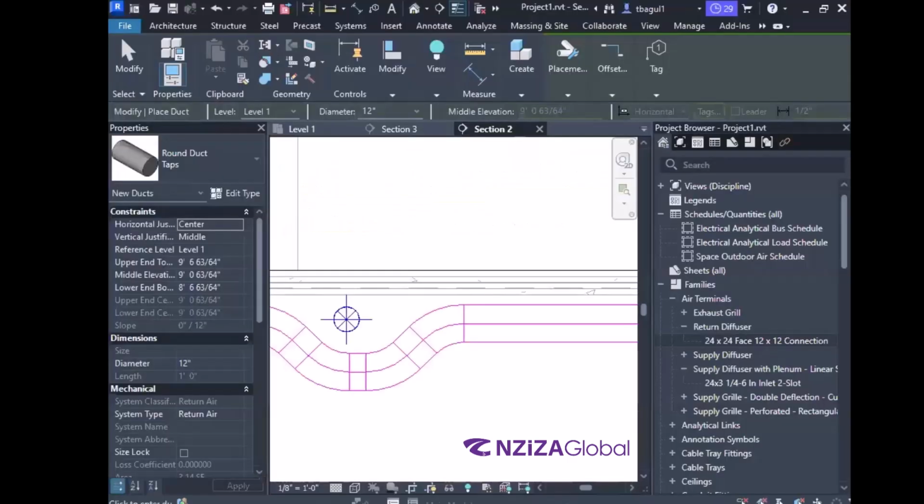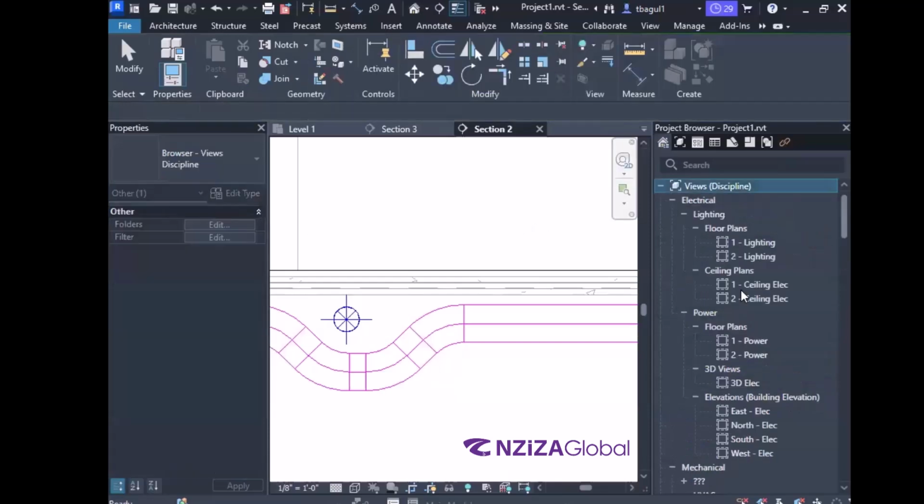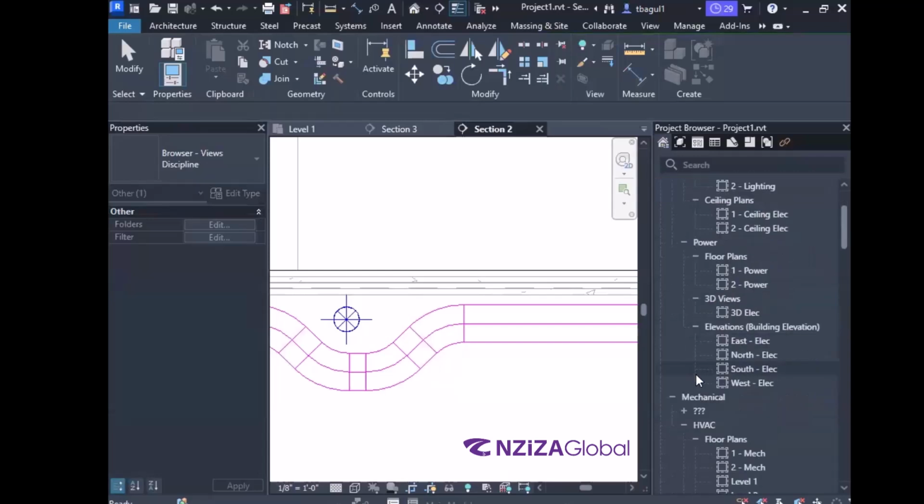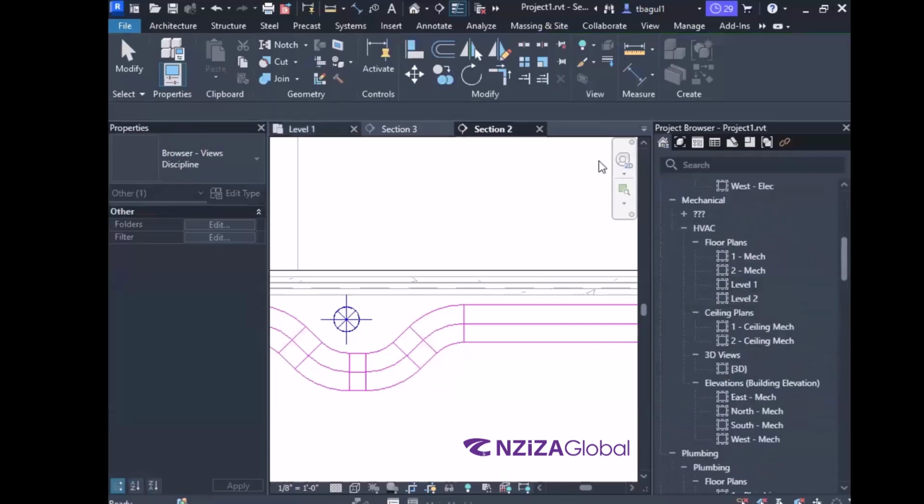Okay. Now coming back to Revit. All right. Now, when we were talking in Revit, at the very beginning when we started the project, we saw there is a mechanical template, electrical template, plumbing template, but we selected the systems template. Why is that the case? Because we want one model for the 3 systems: mechanical, electrical, plumbing. All right. Till now, what we were working on was the mechanical floor plan. All right. Over here, as you see, this particular floor plan that was created was in the discipline of HVAC.